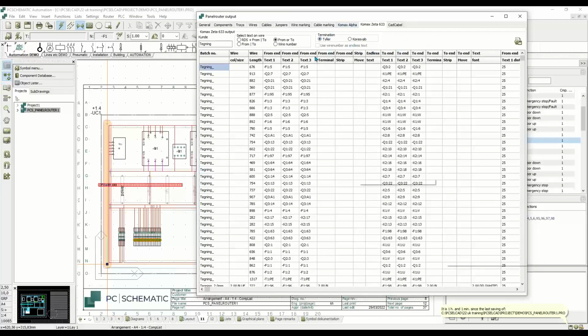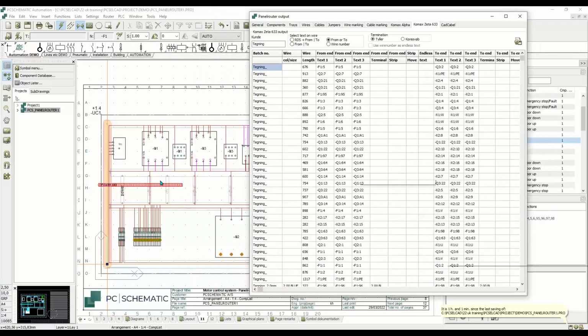So that's it. When we make our drawing, we simply go in and put all those wires in according to the rules that we set up, and that would mainly be this routing class. Then we'll check, is this the right position of it? And we'll route again or put some more of those obstructions, or whatever they call the full stop lines, in here.